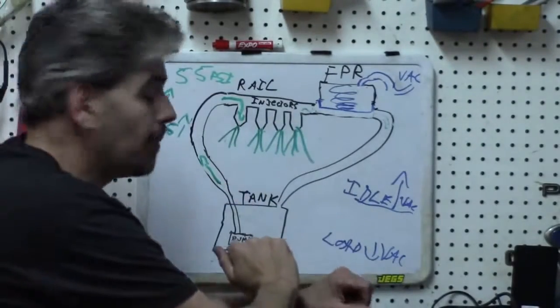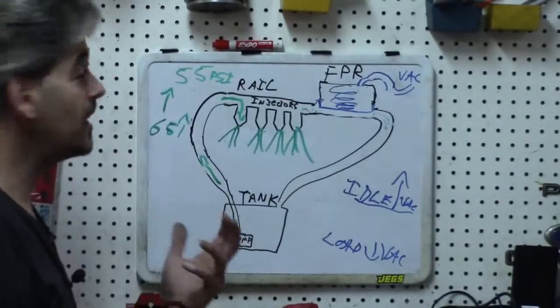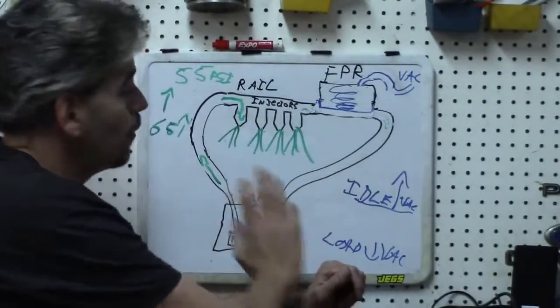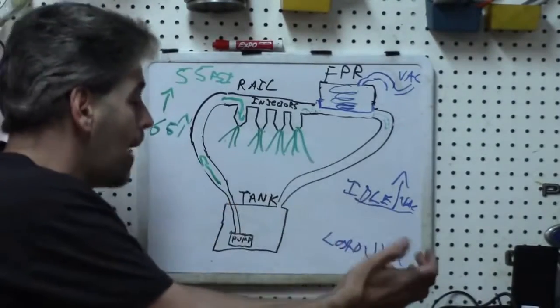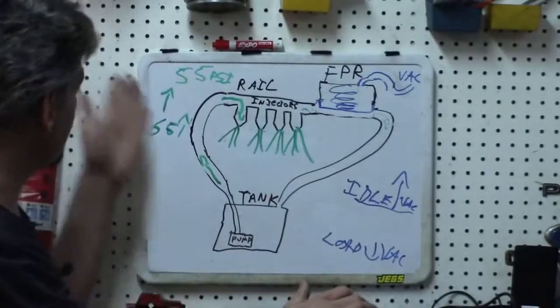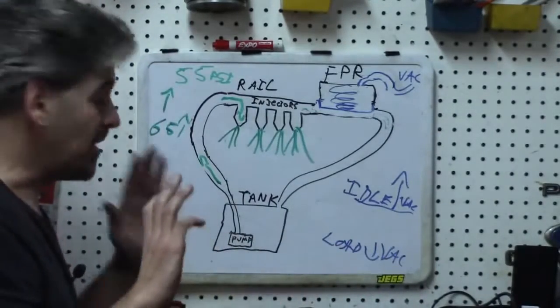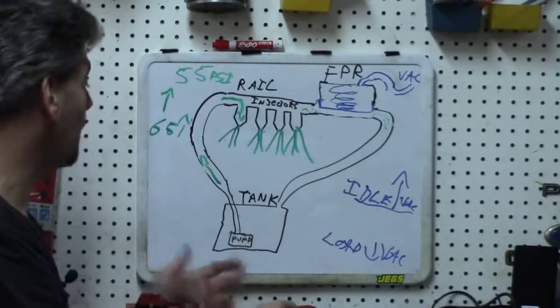Now, another problem that you may have is when you continually have a lean condition, and you do your fuel pressure test and you determine that you have low fuel pressure. Obviously, the first instinct most people are going to have when they find they have low fuel pressure, probably 70% of people, is to just go ahead and replace the pump thinking the pump is bad.